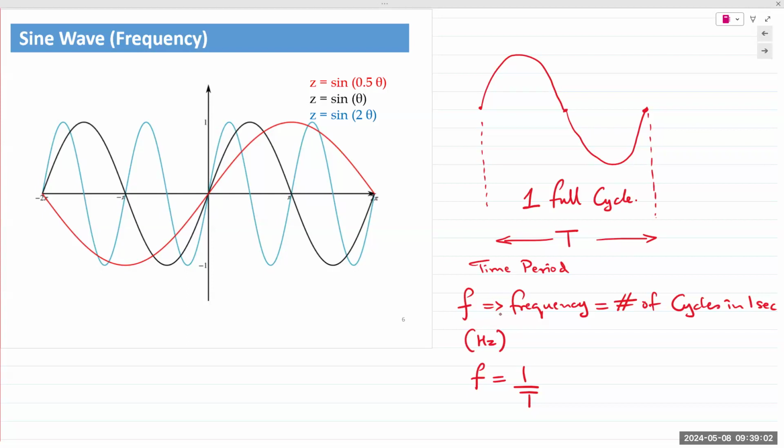Okay, some of the typical values of the frequencies that we see in signals around us. Let's take AM and FM radio. AM is amplitude modulation. You have the number of a station or the name call sign of a station. It says 680 AM. That 680 AM technically stands for 680 kilohertz of frequency. That is the broadcast frequency of that radio station. 101.7 FM stands for 101.7 megahertz, 10⁶.